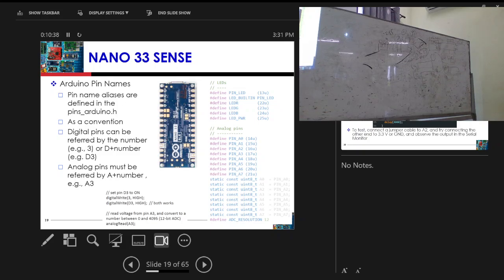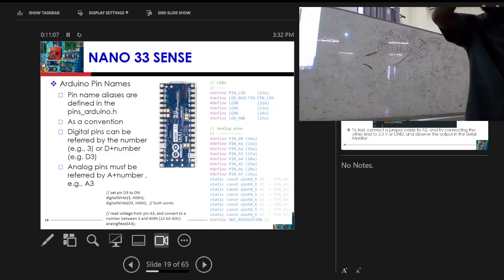So you see how easily you can be tricked. For the pins, you can use A3 to declare an analog pin. But if I just say 3, you say what? As easy as that. Otherwise you are just confused. It will be an error in your code.